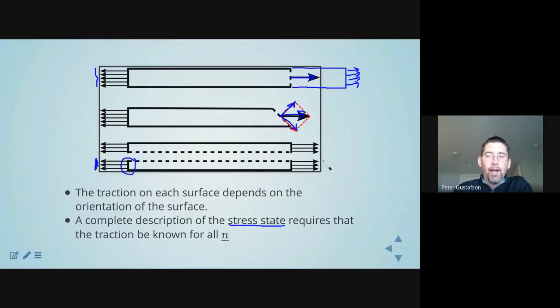If we look at the right-hand side now, because there's no cut on that interrupts the flow that goes through here, now we have a uniform stress on the right-hand side, and it has an associated area. So this area times this distributed force plus this area times this distributed force, these two things identically balance each other out. So even if I drew a vector here, we would know that the components of that vector actually have to be 0, both in the normal direction and in the shear direction. So does that make sense, Caden?